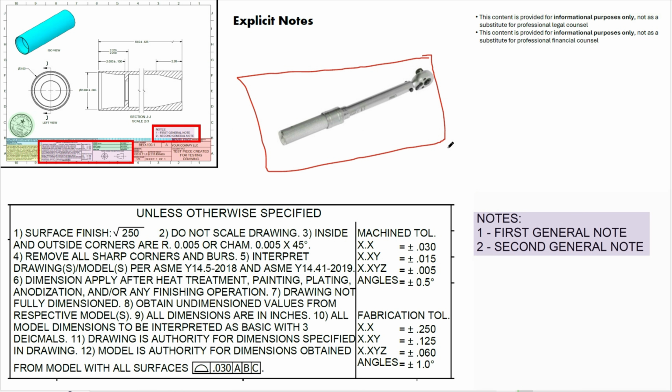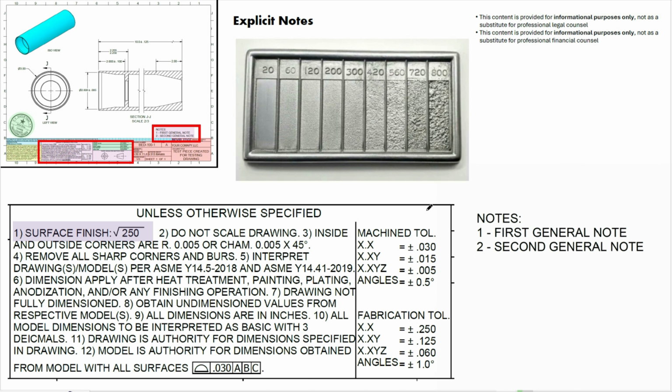Or if you're using something that is of a certain tolerance or a certain off-the-shelf product, make sure it is this kind. Those are the notes explicitly called out inside the drawing, in the blank space outside the title block, and they are variable from individual drawing to drawing. These can change on the fly, whereas the things in the title block usually stay constant.